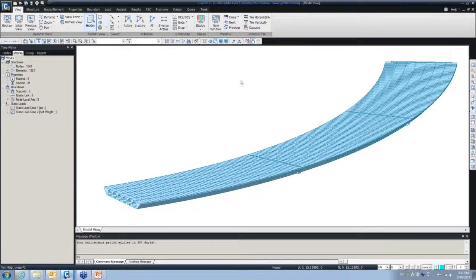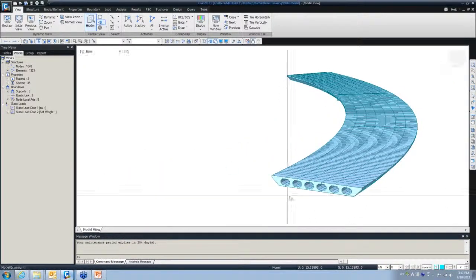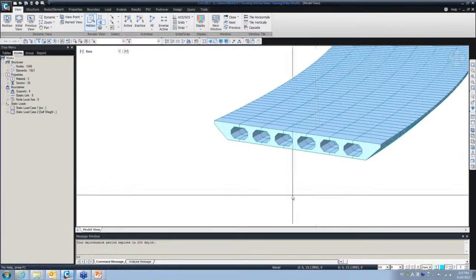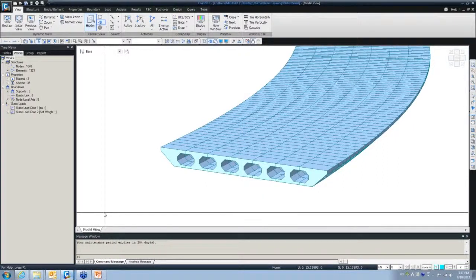All right. So this is the model that I'm going to create for you today. As you can see, this is a wide multi-cell box. Here I use the Grillage model. The Grillage modeling is a wizard created in Midas Civil just to make it easy to create such bridges, wide multi-cell boxes. This wizard was generated based on a Caltrans request, because this type of bridge is pretty common in California, but it's useful for any other states as well.